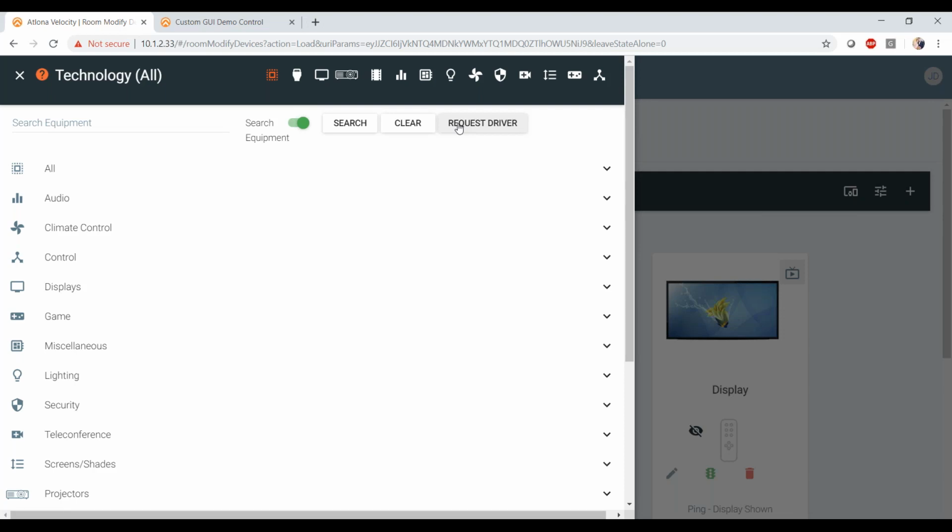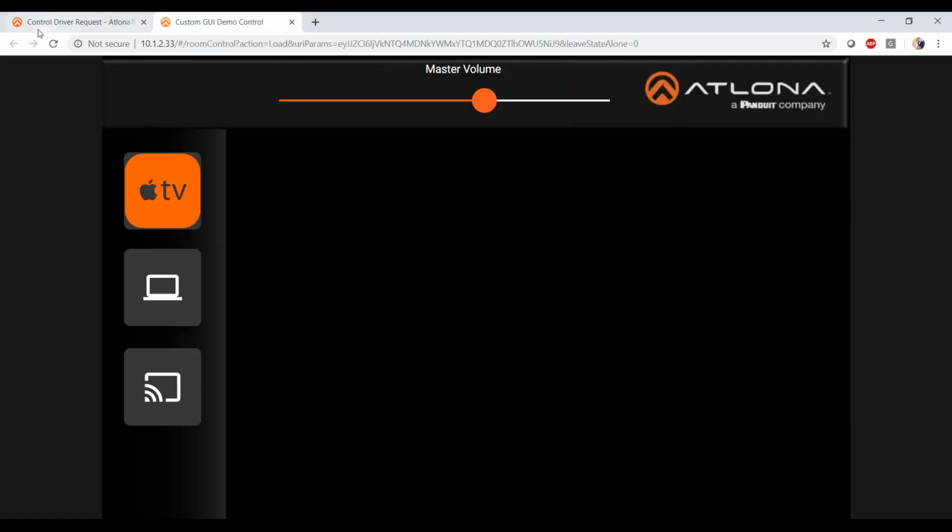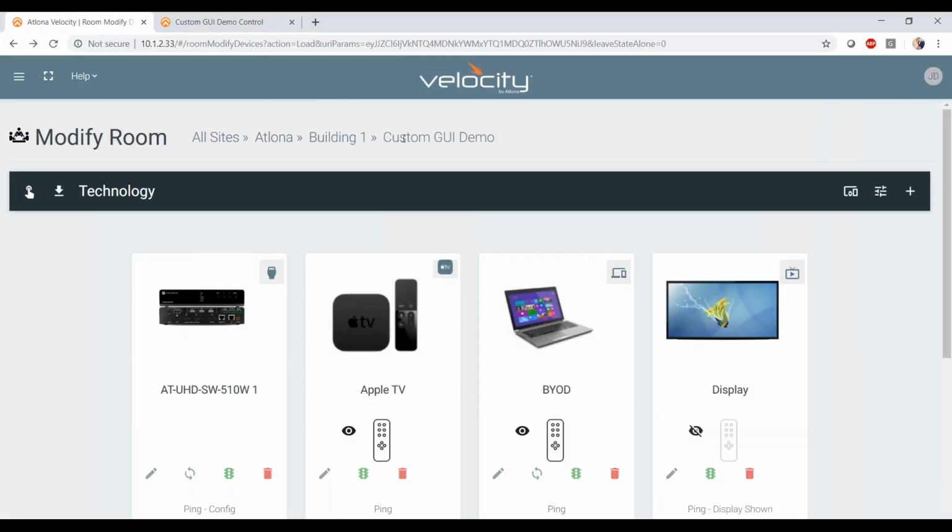And so now when you come into Velocity and go to place that driver somewhere, on a button press for example, it's going to give you a drop-down menu. What input are you selecting? What output are you selecting? Okay, now it knows. Let's say we're doing input 5 to output 7. So you drop down, select 5 on the input, drop down, select 7 on the output, and now it knows it's sending 5 AV 7 %0D or whatever, right? So yes, we would be able to control that. There are a handful of ways you could go about doing that, but suffice it to say, it would be simple enough to get something like that done, yes.